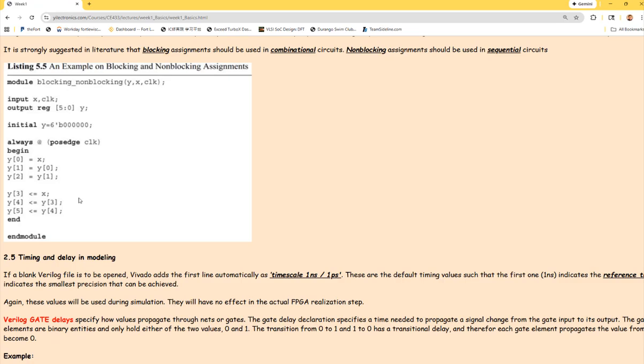So come back to the question: why are FPGAs usually faster than microcontrollers? So first, they usually use a newer technology, right? And their transistors are smaller, so they can run faster, and their VDDs are smaller, so when charging and discharging with a higher frequency, it's able to drive it compared to the bigger technologies like Arduinos.